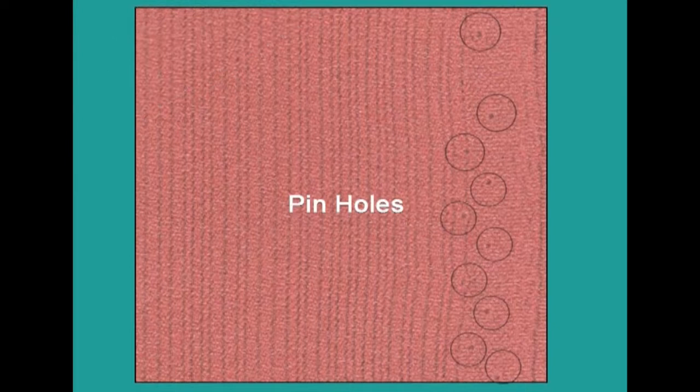And we have another defect called pinholes. Pinholes along the selvage are caused by pins holding fabric while processing through the tender frame. It becomes a major defect if pinholes extend into the body of the fabric far enough to be visible in the finished product. Most of the fabrics which are tendered will have these pin marks if it is a pinned frame, and if it is a frame consisting of clips, then you will not have this kind of problem.